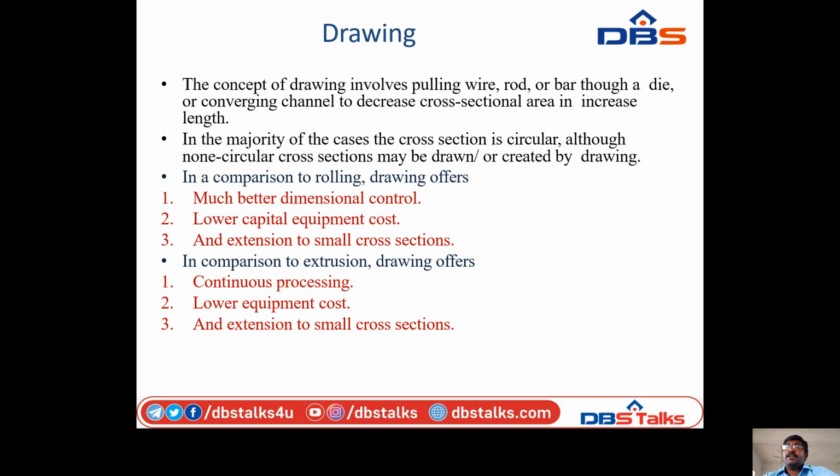Drawing. So what is drawing? The concept of drawing involves pulling wire, rod or bar through a die or converging channel to decrease cross-sectional area and increase length. In the majority of cases, the cross-section is circular, although non-circular cross-sections may be drawn or created by drawing.